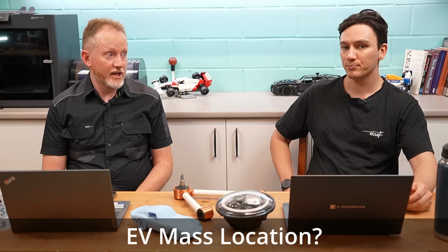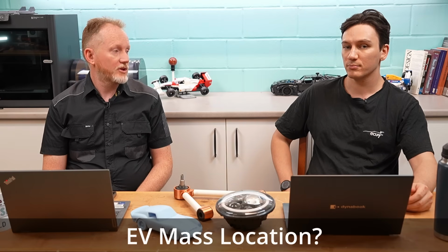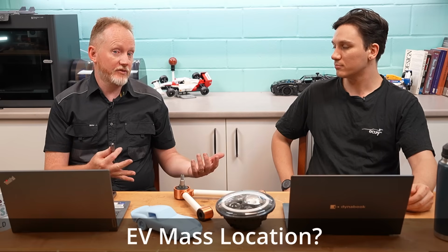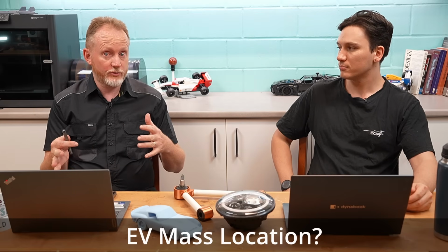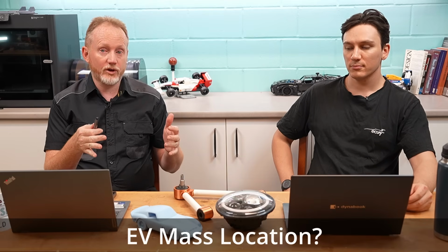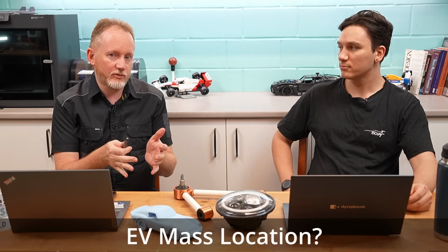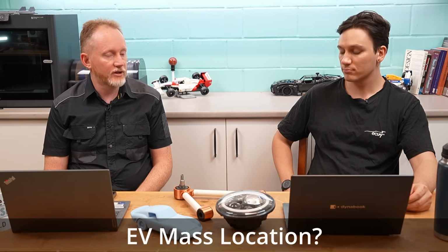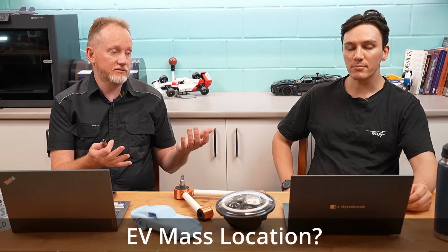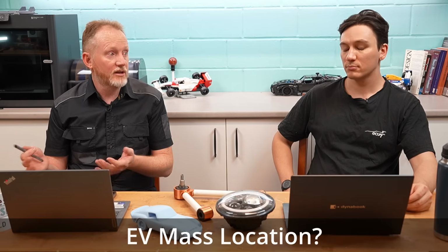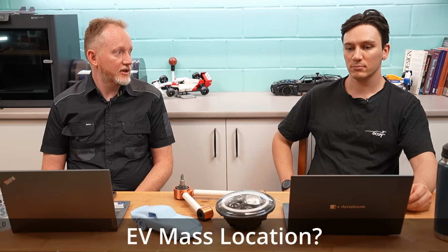I think from a vehicle dynamics point of view, there's so much you can do when so much of the mass can be moved around. We mentioned in that video that it's very difficult when you're going through the design process to actually get a mass location where you want it, even if you know exactly where you want it, because a lot of the components, once you've placed them, you can't move much. I would love for the center of mass to be around 55% rear, but it's going to be closer to 60% on the rear. And short of adding ballast, I can't do that.